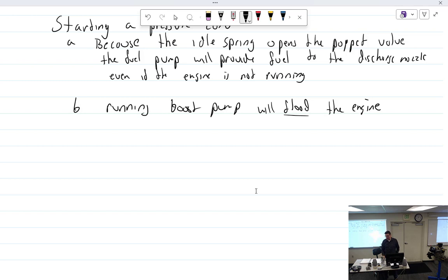And if that happens in a carburetor and you leave the throttle plate closed, there's enough suction that it keeps pulling fuel out of those little idle jets into the carburetor. Well, you're too rich to run, and what did you just add? More fuel. So is it ever going to start? No. So what you do is open the throttle wide open. Now how much fuel comes out of the carburetor? Everybody should say none, because you're on the starter.